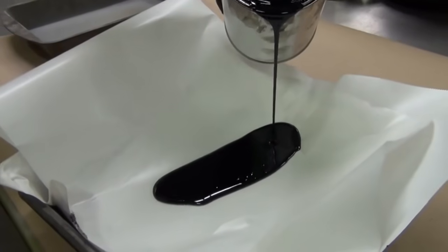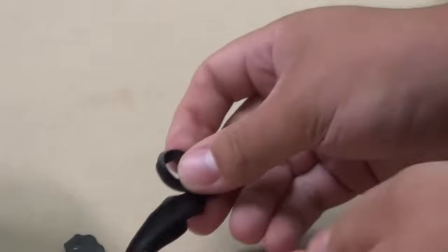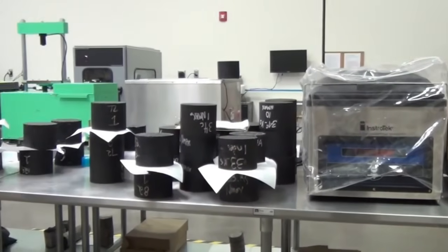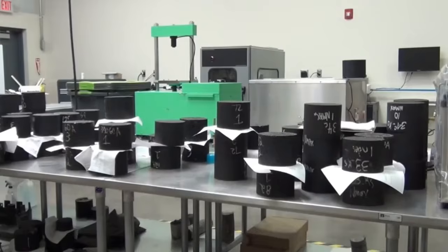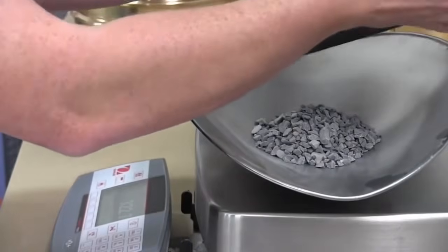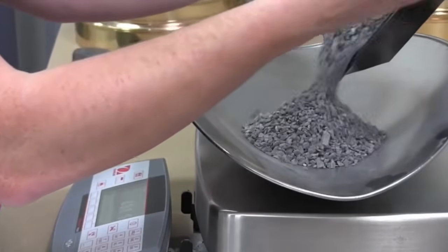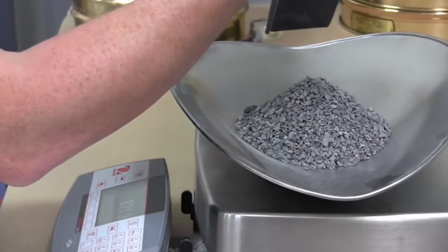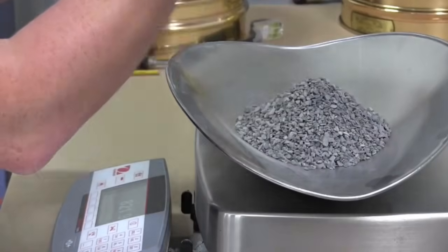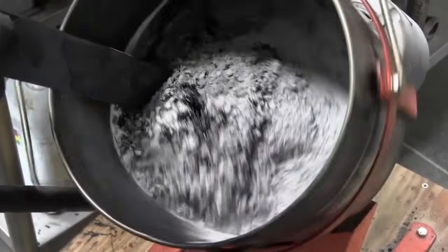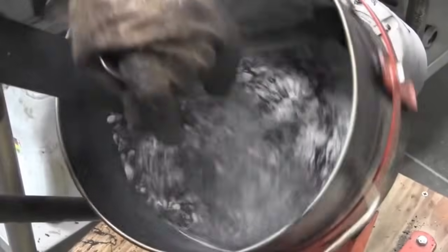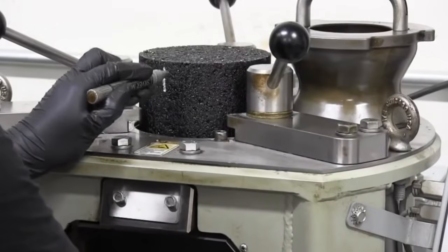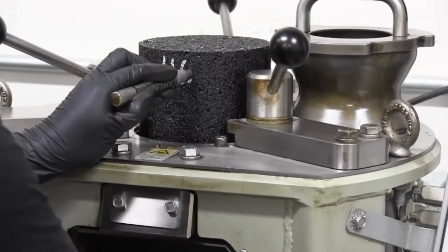The percentage of binder content shall be determined to achieve the requirements set out in specifications and the traffic volume specified in the contract. The Marshall method shall be adopted to determine the maximum percentage of binder content. Normally, the percentage of bitumen used for DBM is between 4.0 to 4.5%. Apart from conformity with grading and quality requirements of individual ingredients, the mix shall meet the requirements set out in the specifications of the project.